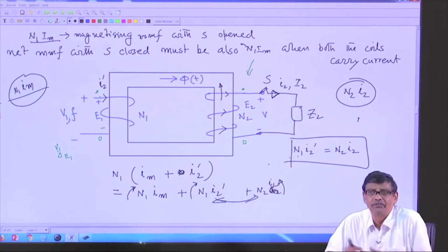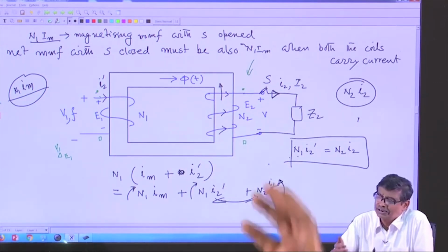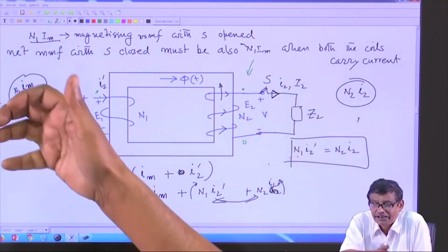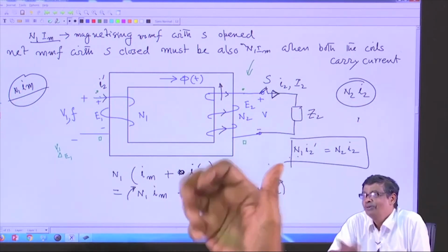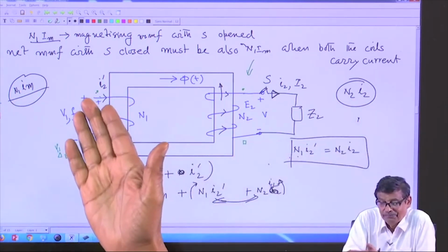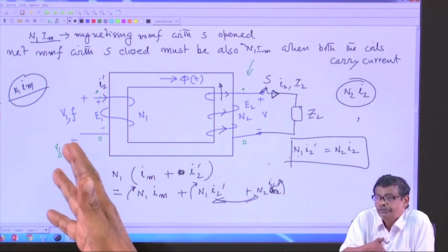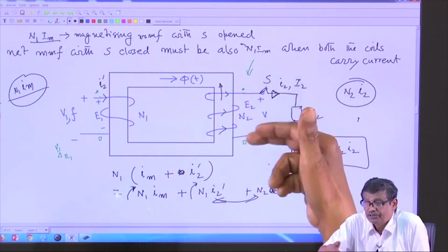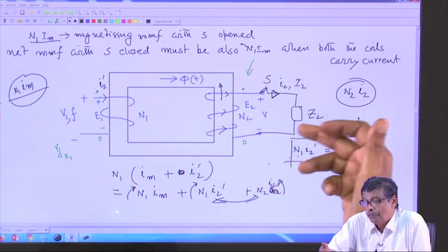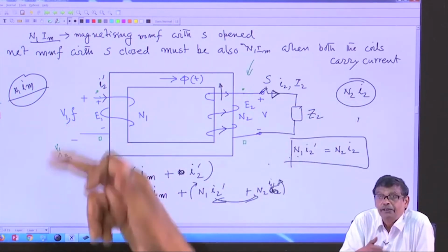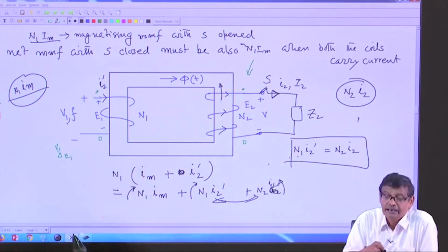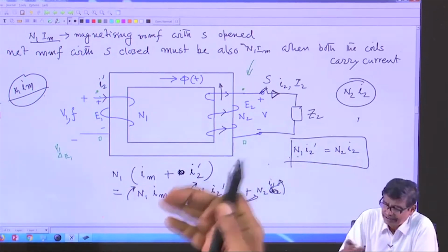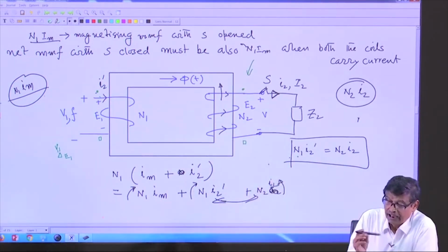There is an easier way of understanding. Look here, if you draw power output from the secondary of the transformer, primary current must increase. How can it? Because these are the only two points where I am pumping power into the system, and you are taking power out of the system between these two. Therefore, if you consume power here, ultimately power has to come from this place here. Therefore, this power must balance. We will discuss those things later, but I hope you have understood.